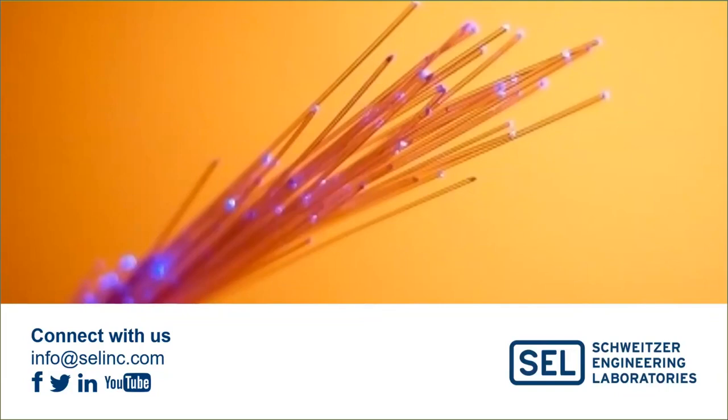We have a question here that says, is there an amplifier for 1550 nanometer single mode when fiber length exceeds the 120 kilometer limit? SEL does not make amplifiers. Of course, once you reach your 120 kilometer limit, you can put in another piece of equipment, another termination. Let's say at 120 kilometers you would want to add a node there, or maybe add another transceiver that can regenerate that signal. But we don't have an amplifier that SEL makes that I'm aware of.